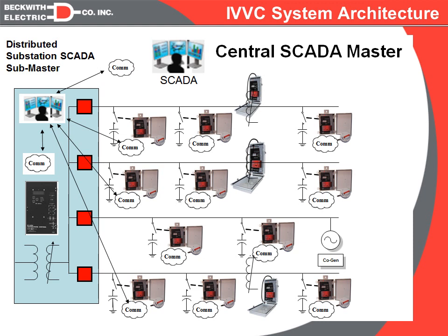In this case, we would not want to use the standard heartbeat, because if we were to lose the communication link between the SCADA and the RTU, the RTU would still be polling, the controls would still be seeing valid communications, and therefore they would remain in remote manual even though the centralized system can no longer send commands down to them.